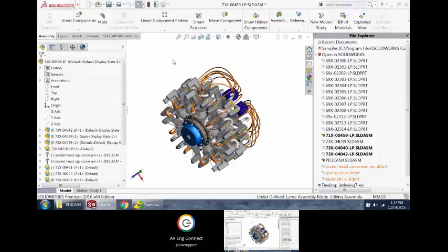If it's flexible, it has to load those all up so that it can solve them when I go to move it. If I turn that flexibility off, all of a sudden this thing's not going to move at this level. It'll still move at the subassembly level, but it'll make this assembly solve a little bit faster because it's got that many less mates to have to bring in and calculate for where the position is on everything.